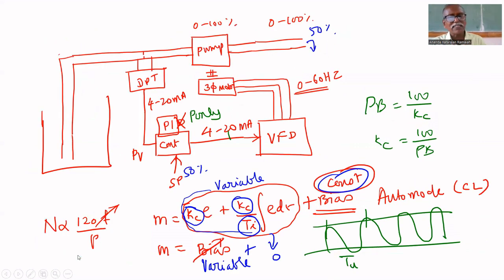You can find K max just in the controller. You are decreasing PB, and at one point it exhibits sustained oscillation. That is the required PB, that is PB min. For Kc we have to take max, but for PB it means minimum. If you multiply Kc max by 0.45, then for PB you have to divide by 0.45. So you got PB min, and the required PB equal to PB min divided by 0.45.